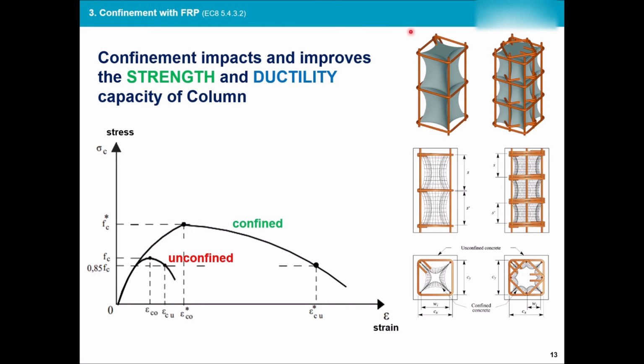Now this is a good 3D schematic of what a confinement can do. The gray bits are the bits and pieces of the concrete which are supported in terms of confinement, so they won't change in terms of area. This is in a normal situation that you have just some reinforcement, shear reinforcement with some spacing. You can see that the 135 degree closing of these ties is at least applied. There is another schematic of it.